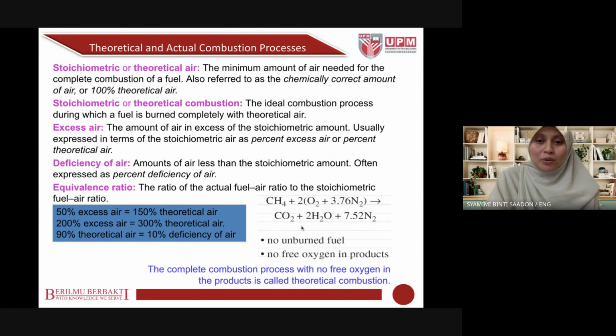So if we put in enough stoichiometric or theoretical air, there is no unburned fuel and no free oxygen in the products. This is an example of a chemical reaction equation of methane CH4 with air, where air contains oxygen and nitrogen. The complete combustion will produce carbon dioxide, H2O, and nitrogen. The complete combustion process with no free oxygen in the products is called theoretical combustion. No oxygen left.